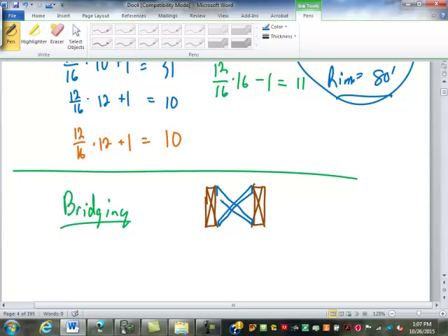And that is in between them. Yes. Bridging. Now if this is 16 inches on center, that means this distance is only going to be 14 and a half or 14.5 inches, right? Subtracting the 1.5 inch thickness of the joist. The length of that bridging then depends on the height of the joist, whether this is 2 by 12s, which would be 11 and a quarter, I joists would be 11 and 7/8 or whatever.